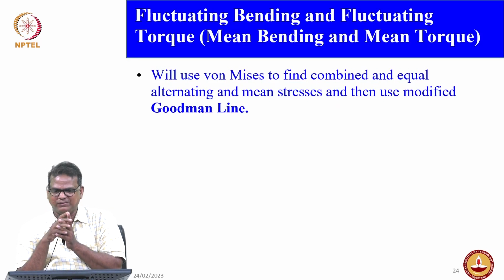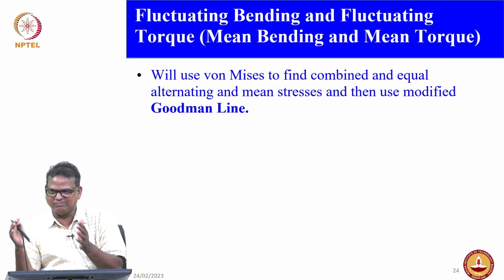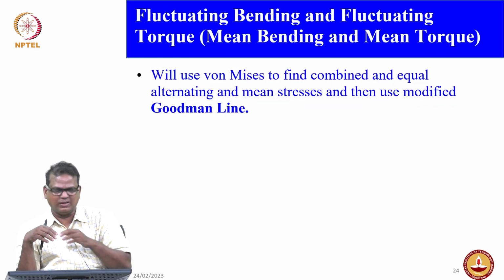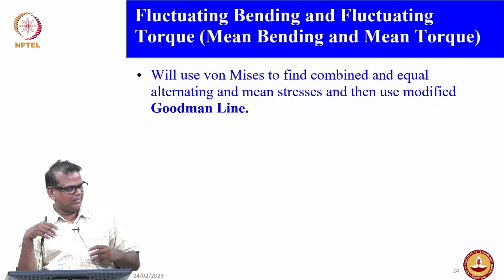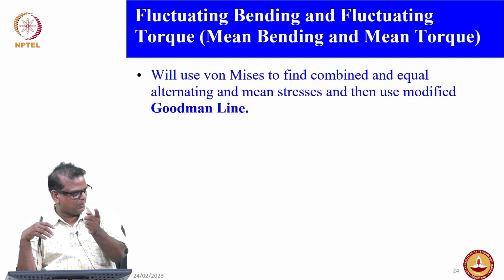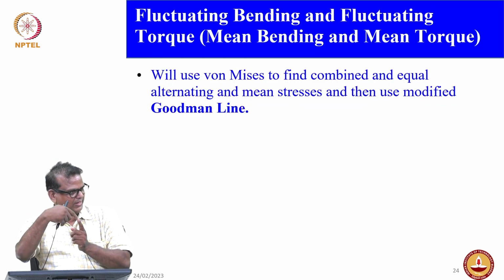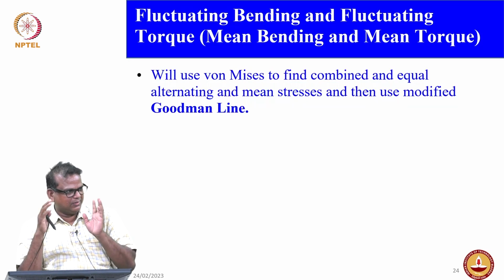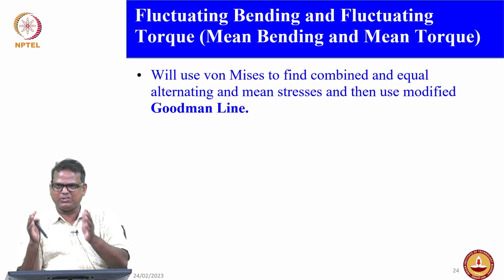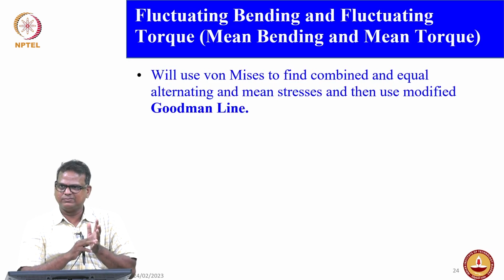Torque is variable. So variable means fluctuating, right? It is fluctuating. Okay, that's one thing we got. Already from the lay shaft we know what is happening to the bending also, right? The same thing would reflect to the corresponding contact reaction forces. So obviously the main output shaft is subjected to fluctuating torque and fluctuating bending, right.